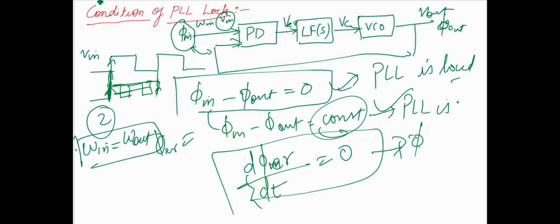See in this waveform which I drew, this rising edge, then another rising edge coming. There is a problem comparing these waveforms, so we have to make this frequency equal to that frequency. For example, if at the input you are giving 1 megahertz and at the output you are receiving 5 megahertz, how will you compare the phases? For that you have to use a divider. You use 1 by 5, so what you get is 1 megahertz.